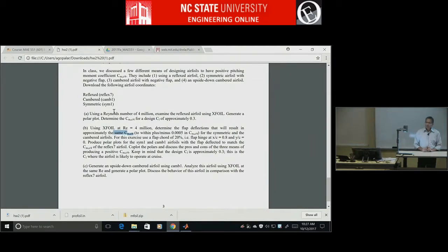You do it exactly the same way that you do for Xfoil. I guess for Xfoil I've given you batch files so you can modify them. But for pplot, you essentially open an editor and you open pplot, and you go through all the motions in pplot that you normally would, right? You would first load up some Xfoil polar. So you'll say 1 and then the polar file name. And as you're doing that, go to your editor and write those commands one after another.